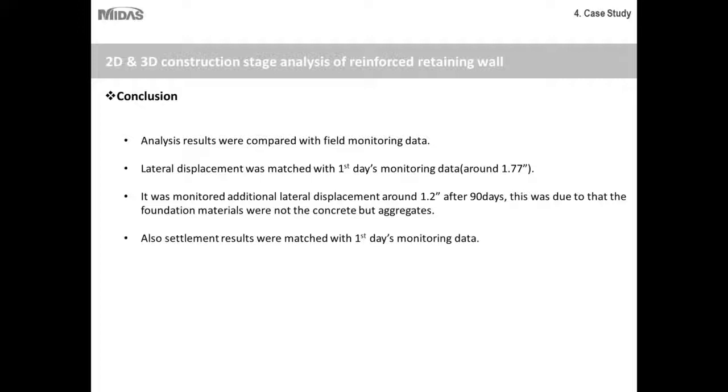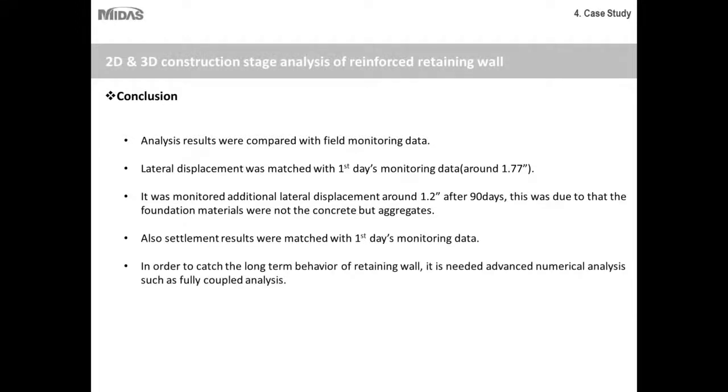So the settlement results became very important, and they had to first monitor the settlement that is going on in the field and compare it with what they were getting from the model file, and they were able to get the perfect match for the first day monitoring data. So like I said, in order to catch the long-term effects of the retaining wall, it was needed to do advanced numerical analysis such as fully coupled analysis. So that led to an advanced set of analysis that needs to be performed, which is not commonly done when you are dealing with very conventional, simple, straightforward retaining walls.